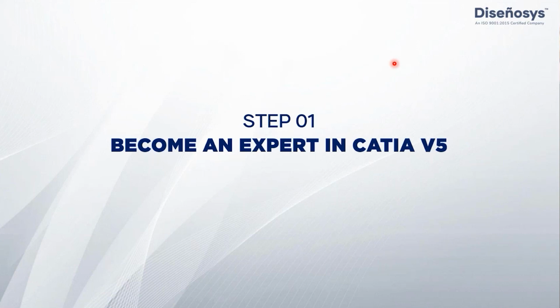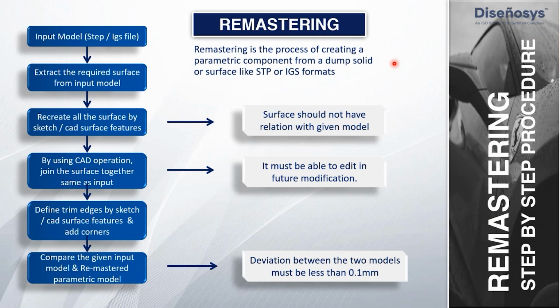We need to have very good advanced knowledge of CATIA remastering. So what is remastering? Remastering is nothing but reverse engineering. When an industry is developing a part, they will scan a benchmark part or an old part. From the benchmark part, we get a 3D scanned file, which is called the input file or the dump model. The dump model would be either a STEP file or an IGES file.